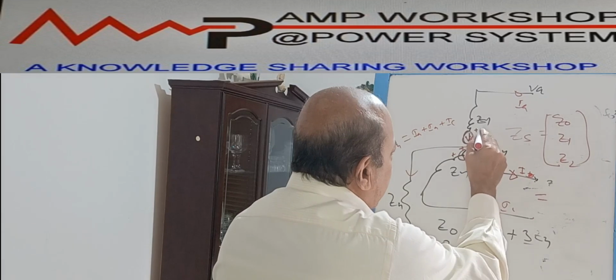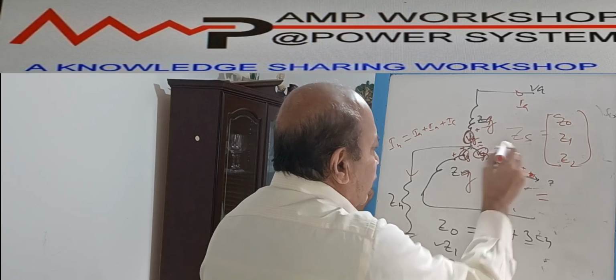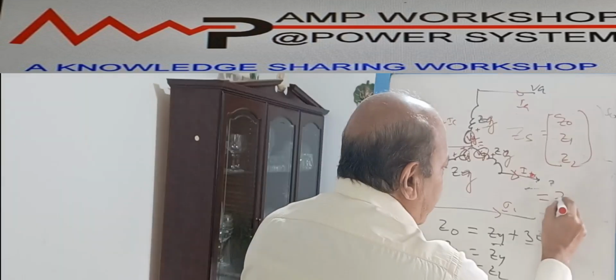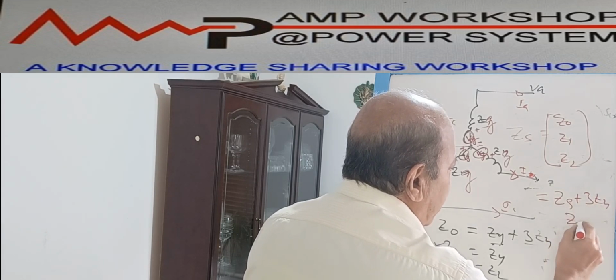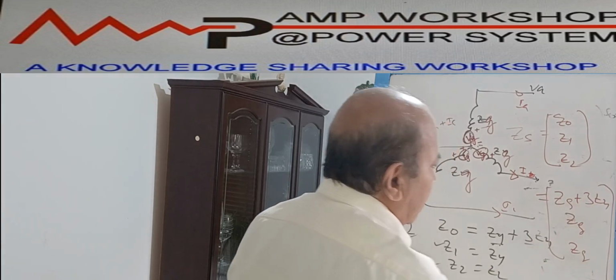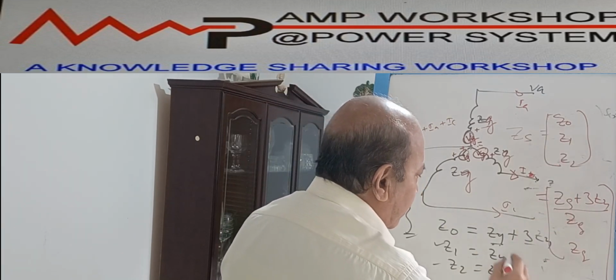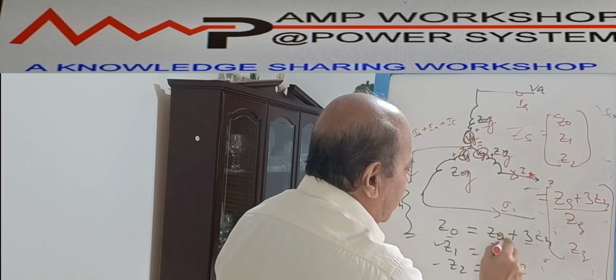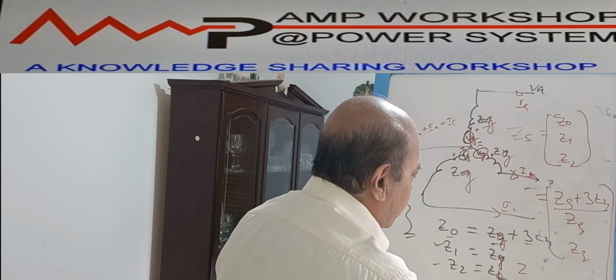Suppose this is a ZG. We are telling this is a ZG. For the generator we put ZG. Then it will be ZG plus 3ZN. And positive sequence will be ZG, negative sequence will be ZG. So this will be the single matrix. So Z0 equals how much? This will be Z0, same like ZG here. Z1 is equal, it is ZG. Z2 is equal to ZG.